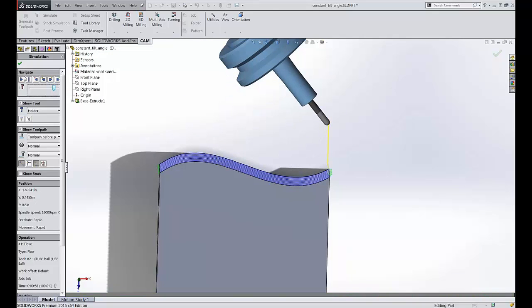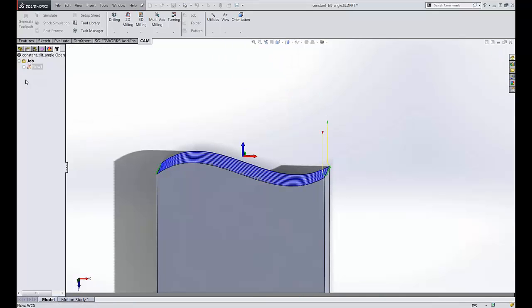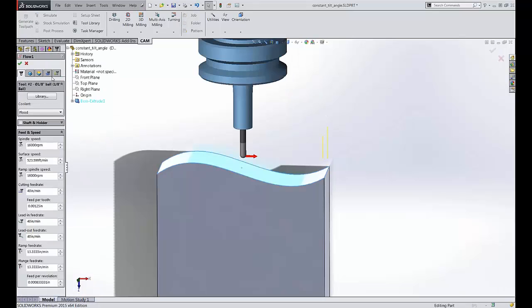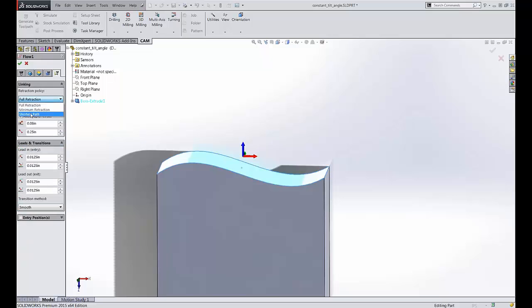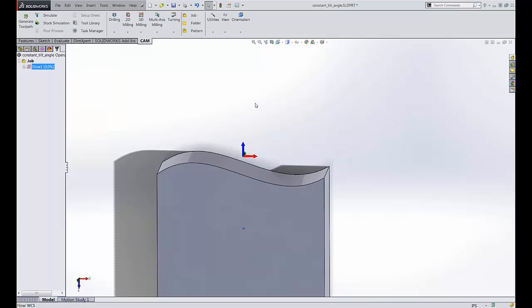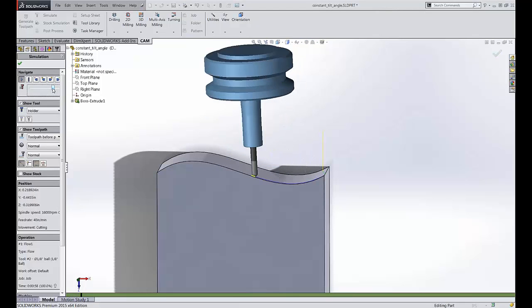In reality, what that does is it gives you lead tilt in one direction because we're tilted onto the front of the tool. But when it heads back in the back direction, you have lag tilt. And you probably wouldn't really want that, so you'd want to swap to using a one direction instead, and probably go on the shortest path. And that way we'll get lead the whole time.